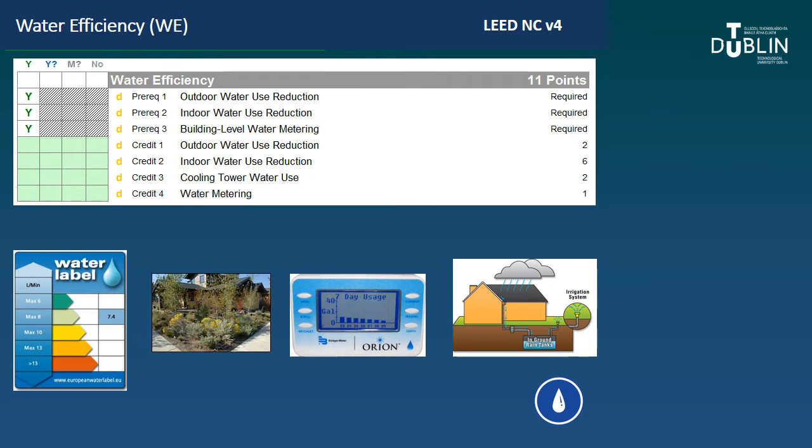Water usage metrics, again, are given in the manual, but it's things like litres per flush or litres per minute or litres per hour, and this category requires you to use manual and interactive water use calculators to calculate both the baseline and then your design case, so how far you've reduced that for water efficiency.